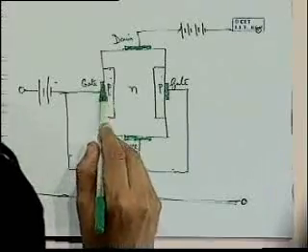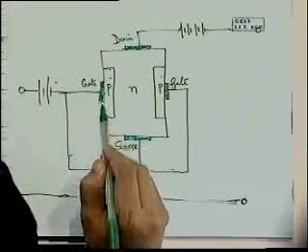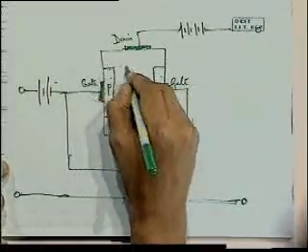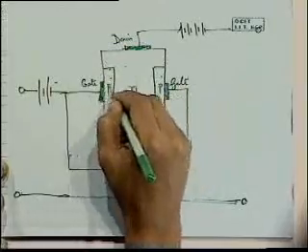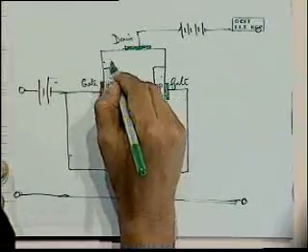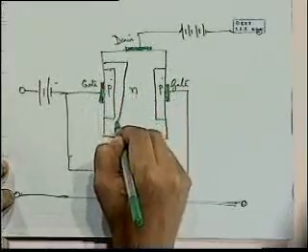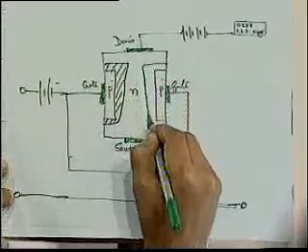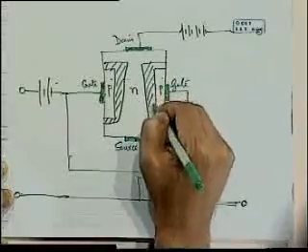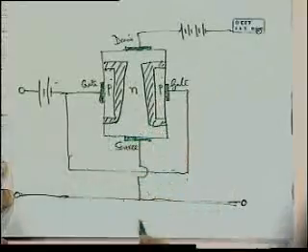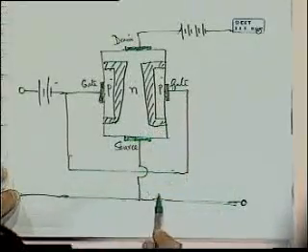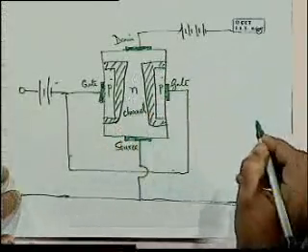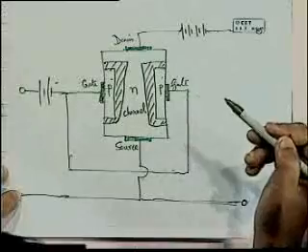What happens when this is reverse biased? We have a depletion layer around it, between the P and the N, which will look something like this. I'll explain the shape in a second. What we have effectively created is the central area, which is the channel between the source and the drain.